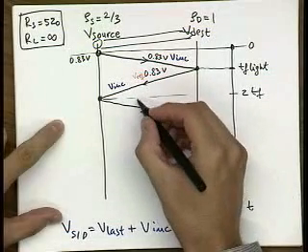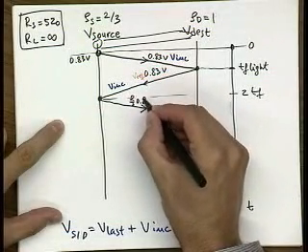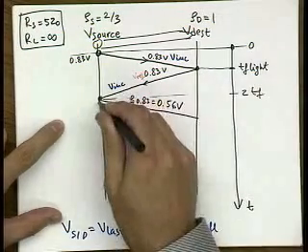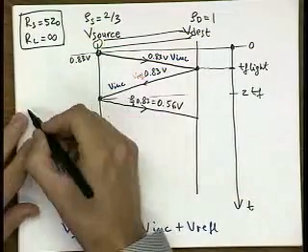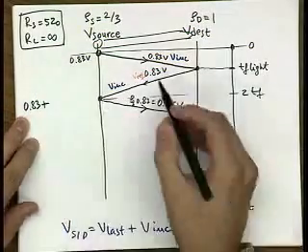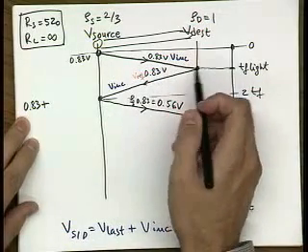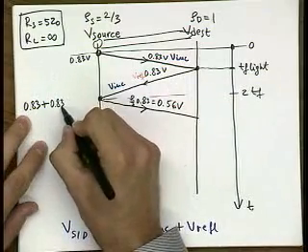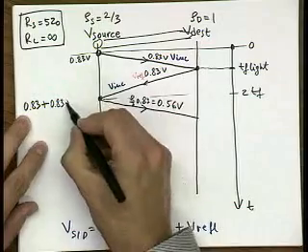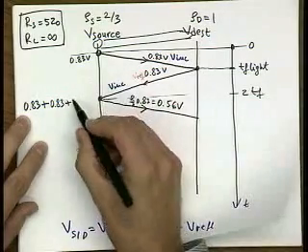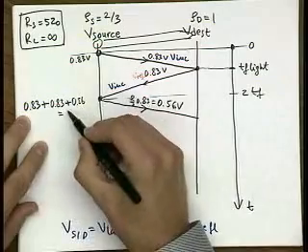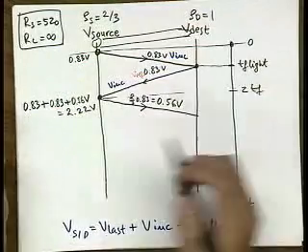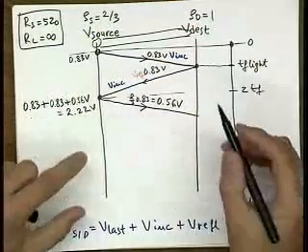So you have 2/3 times 0.83, that is equal to 0.56 volts. Now the value over here is the previous value, so that's 0.83, plus this incident waveform, which was the reflected waveform from the other end, equal to another 0.83, and also plus this 0.56. That's equal to 2.22 volts.